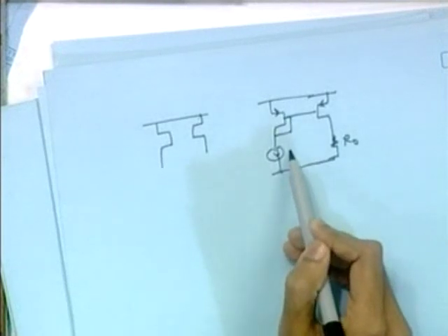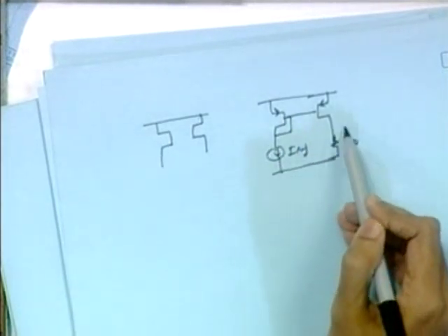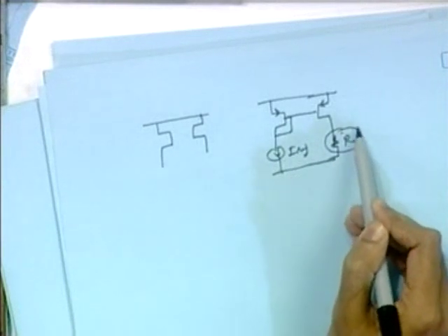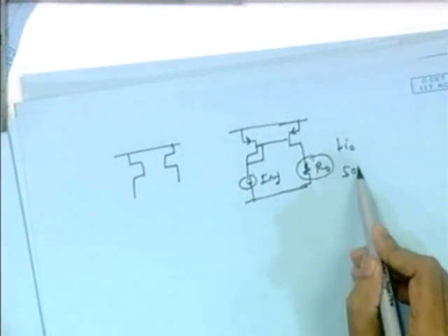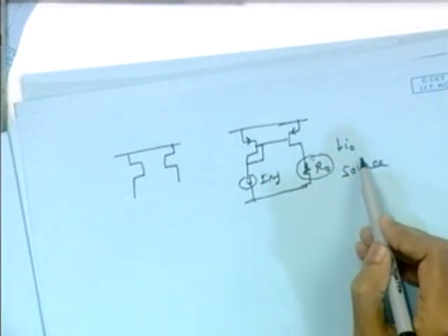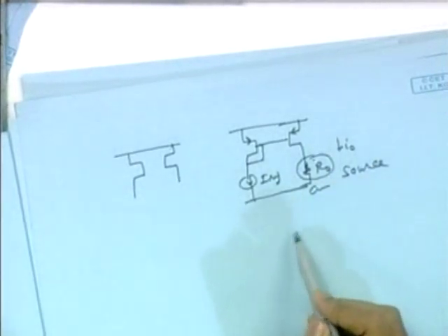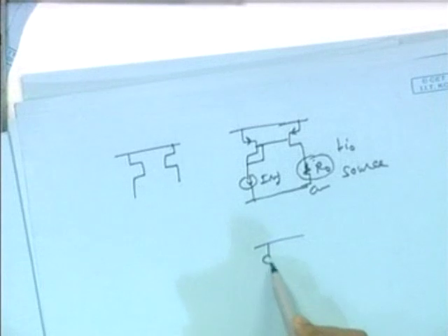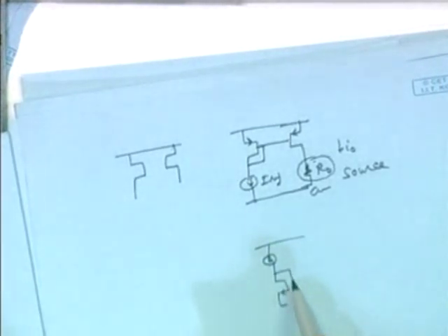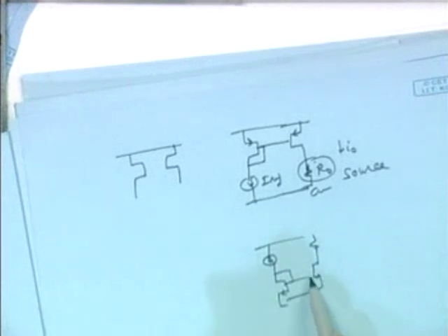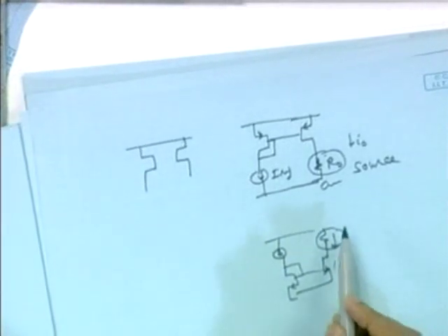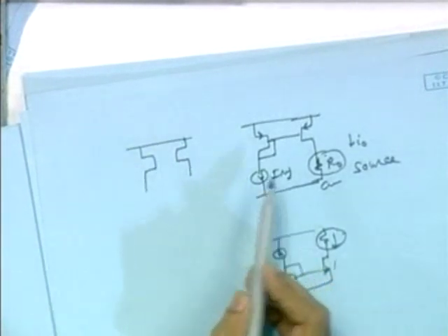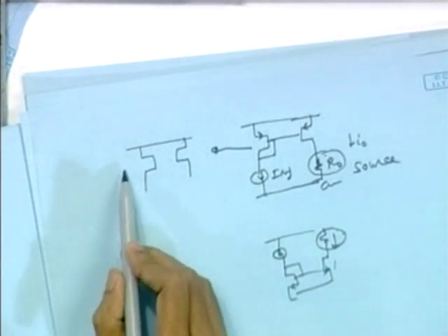This is a PMOS IREF. It sources the current to this load, so the current enters the circuit. So this is called the current source, and the NMOS one basically sinks the current. The current is going out of the circuit and going to the CM, the current mirror. So it is the current sink. For the active current mirror, we use this current sourcing.